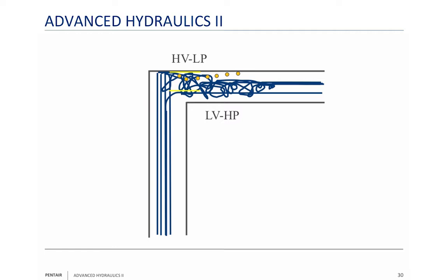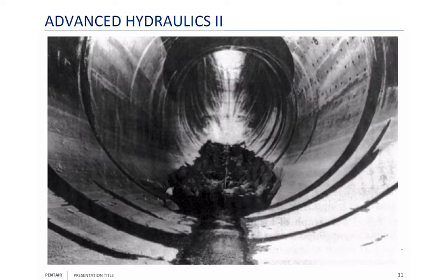Why is it moving to the outside edge of the pipe, you might ask? That's simply because I have higher pressure down here pushing it in that direction. All right? Now, what happens when the pressure gets too great? The vapor bubble collapses and you get cavitation damage.